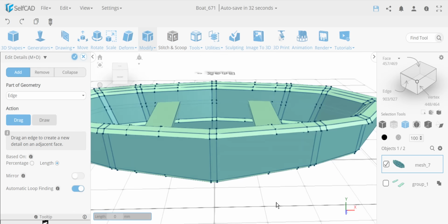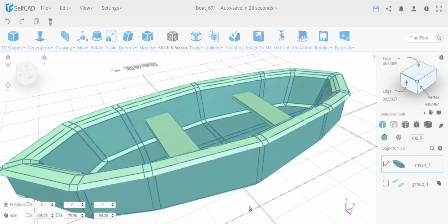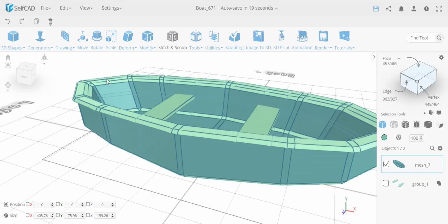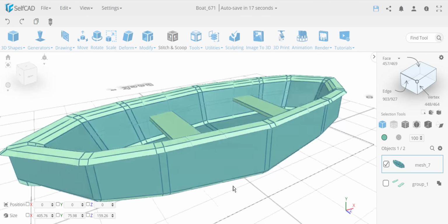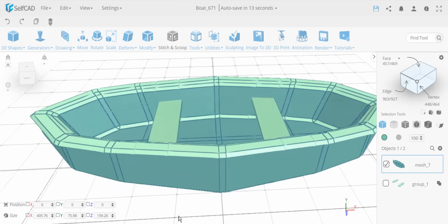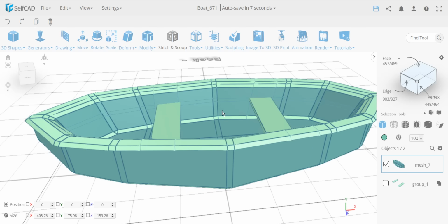Okay, so now what we have done here, we enter the cut, and I complete it. So we have an exact cut that replicates this. Now I've increased the size already to 457 faces instead of 301, and this is because this cut goes through all the way. So every face has been increased, but nevertheless this is still beautiful quads. And if you increase a little bit in quads, that's not a big deal. It's still really nice and still relatively low, but still nice.